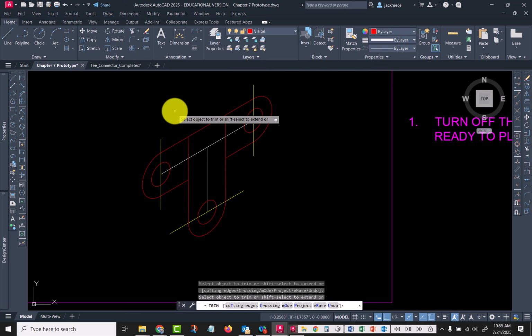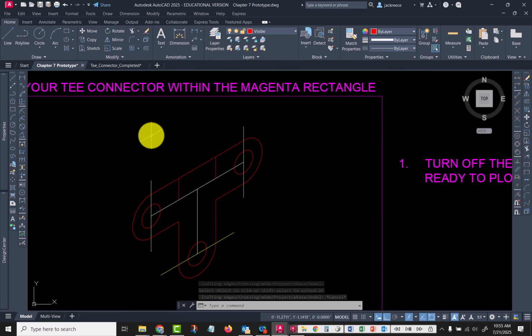Okay. Those are all good. I can trim that part right there. And I want to keep these because I'm going to need them as I'm drawing up. Now, because this thing is an angle, we can't transfer orthographic angles into an isometric drawing. It just doesn't work. So we have to draw an orthographic view of the front of this so that we can determine what the book is showing as distance A.